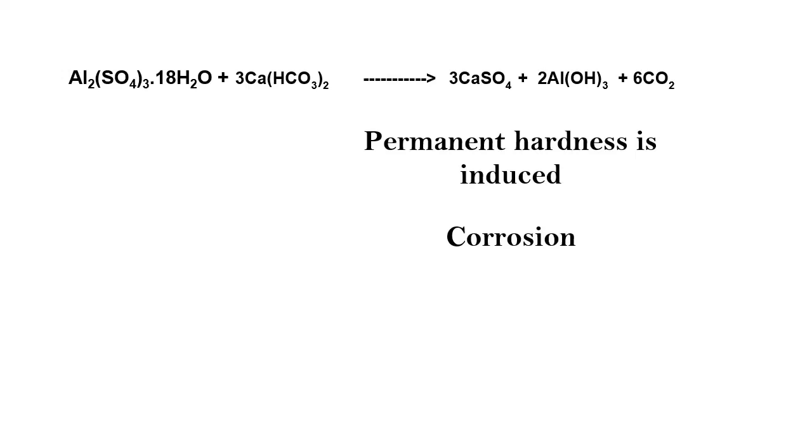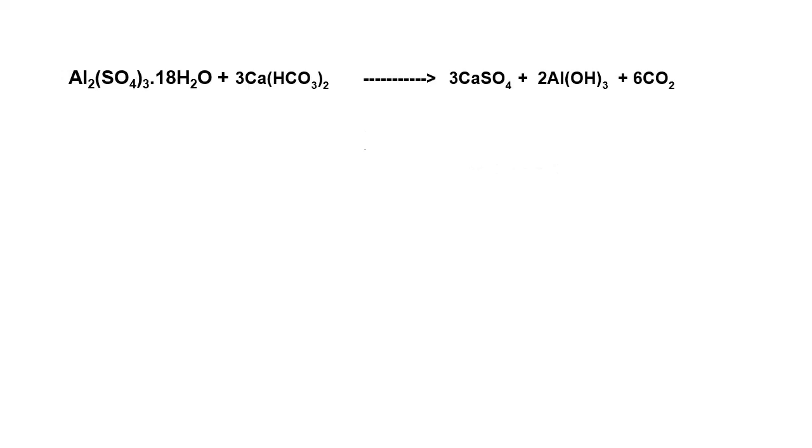But of course it will evaporate, but still the water will have some CO2. This is somewhat dangerous with respect to alum, but alum is a very good product and cheaper in the market. The cost is very cheap compared to others. Understood? Therefore we prefer alum.